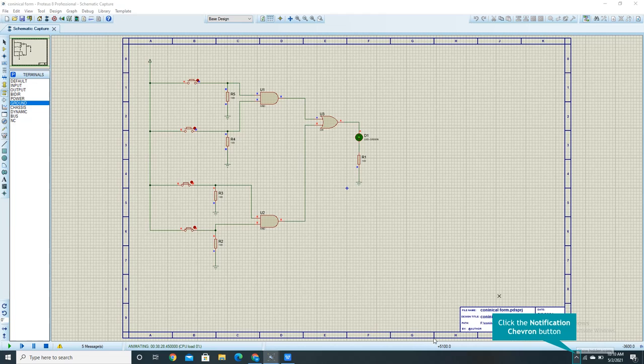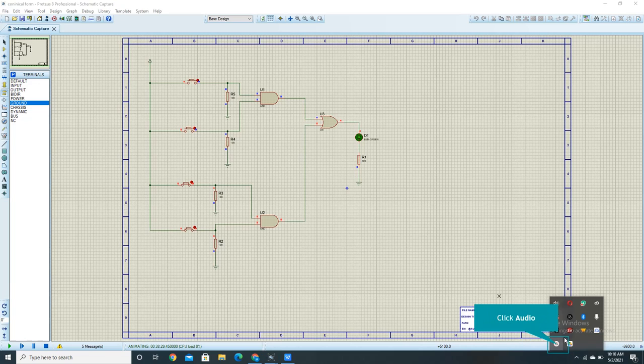So I would simply set C and D to 1 1 logic and it is proving 1. So I would simply set it to 0 0, and you can see it's 0, and then again I set it to 1 1, and that is proving as 1. So by this our circuit is already proven. Now if you want to check the reverse side, if C is positive when D is negative, or A is positive when B is negative, then also this circuit will not be implementing as a positive high logic, and that is proved with our canonical form.